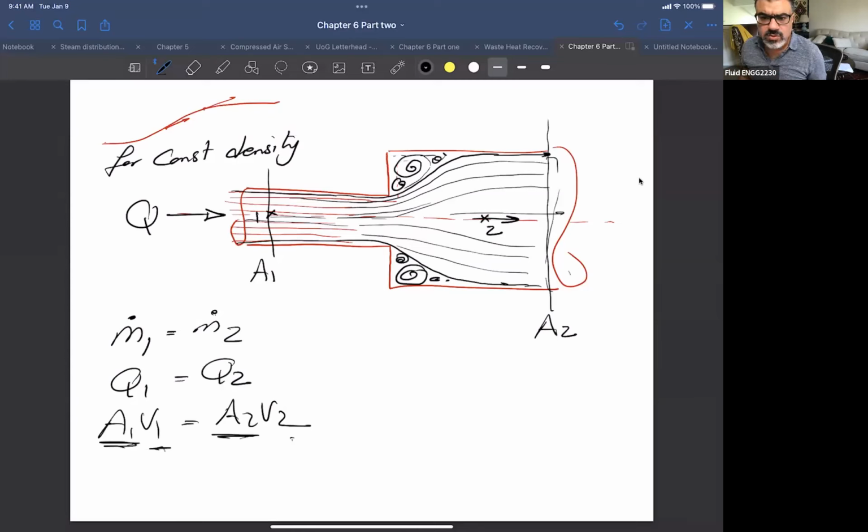So in this case, what we're going to see here is turbulent eddies, right? And those eddies, in order to keep rotating like that, need energy. That's why they take their energy from the energy of the fluid itself. So if you have a fluid going in this direction, this is the eddy that is created because of this sharp change in the cross section.